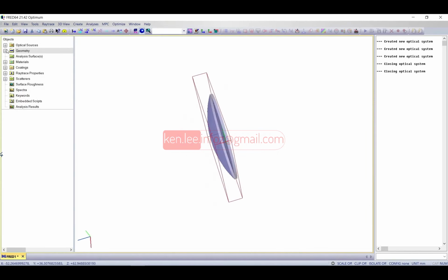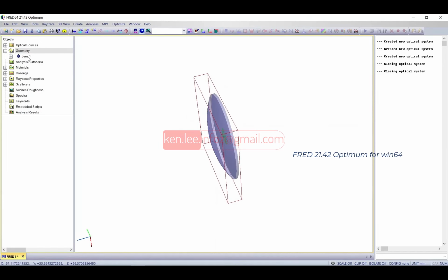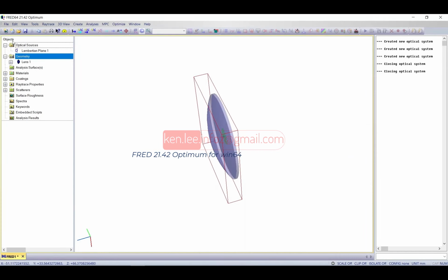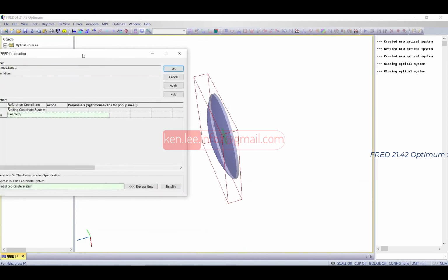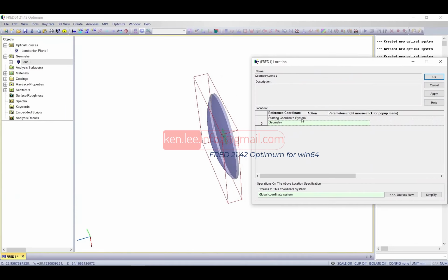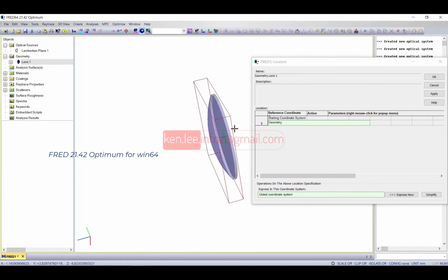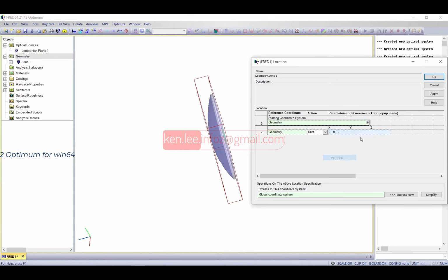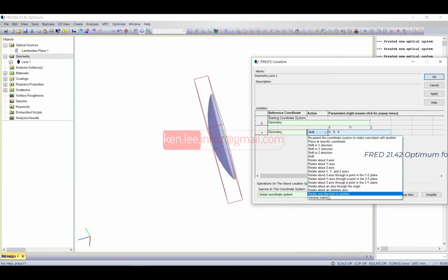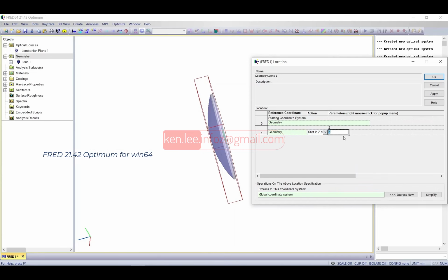Very easy. Shifting the lens, of course. You can see it in the geometry folder, and you can open these items in there. If you click on the lens, right click again, and click position orientation, then you can set up where it is. Every object has its coordinate system and orientation. The zero position in the geometry folder is the starting coordinate system. I can go here, right click and append, and I can shift it, rotate it, whichever operation you prefer. We'll just shift it in the Z direction by, what was it, the 100 millimeter focal length of the lens.